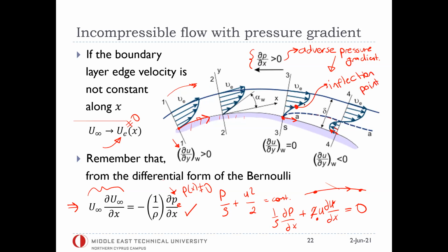So its curvature changes, as you can see, and the specific value of du/dy, which we use to calculate the wall shear stress, becomes equal to 0 right at the separation point. If you move further downstream, this du/dy value even becomes negative, as you can see from the velocity profile, because of this negative, reverse direction velocity field.